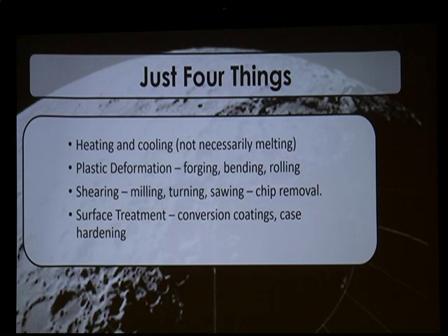So hard, in fact, that when I forged a knife out in the desert about a month and a half ago, I forgot to temper it, and when we chopped through the lamb shank with it, it was a weird party. We chipped the edge of the blade. But tempering, you'll bring that back out. So you reheat after you've done your heat treatment, and you can remove some of that hardness, which makes it brittle, and wind up with a more flexible blade.